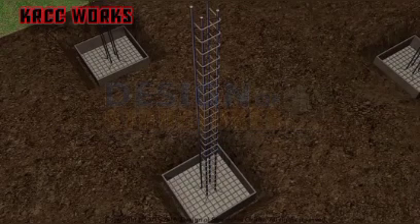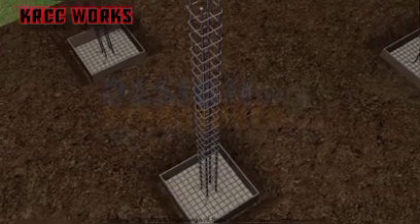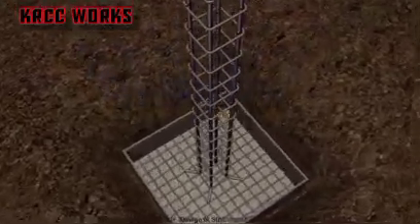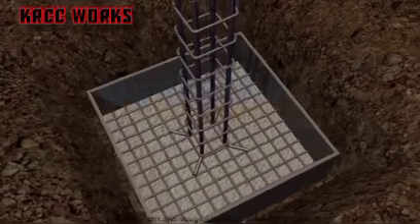The reinforcement shifting and binding shall be started as soon as shuttering is completed. Reinforcement binding shall continue as shuttering work progresses.